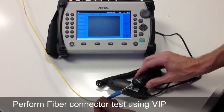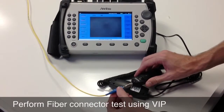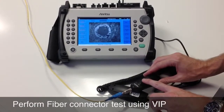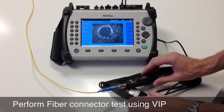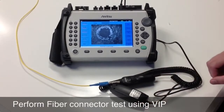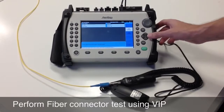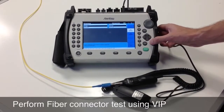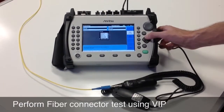Insert the connector into the video inspection probe, and then use the focus knob to get a focused connector on the screen. Before initializing the test, make sure that your probe model and probe tip are selected correctly in the test settings.